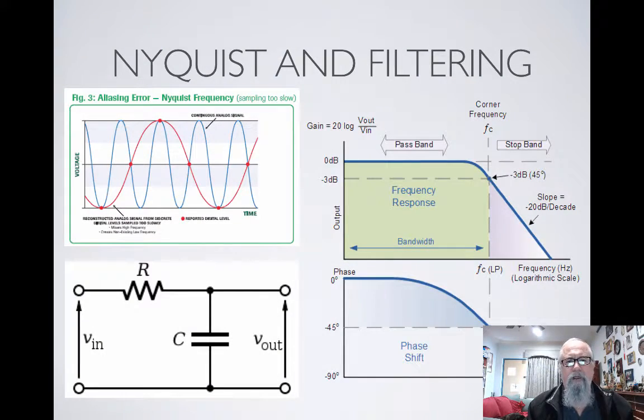Okay, the next thing we have to look at is the filtering. So we've decided on a sample rate. We know we're going to be sampling at least twice the rate of the highest frequency component in our signal. But how are we going to limit other frequencies that we don't want to receive? So again, we look at the voice sample where we have a highest frequency component of 3600 Hertz. We will get clicks, which is a high sort of frequency. We will get other noises in there that we don't want to capture. So we need to filter the signal selectively.